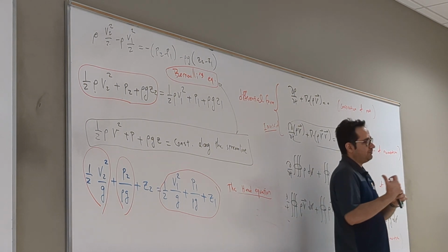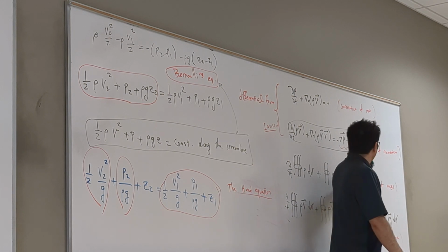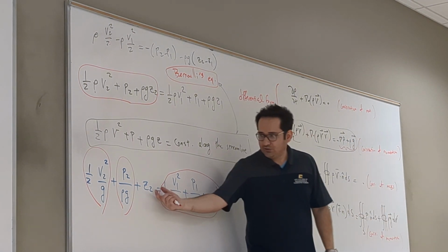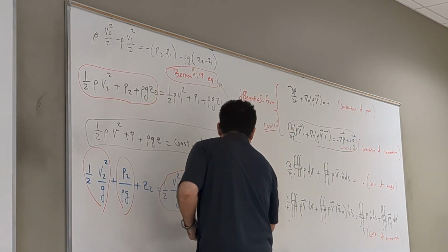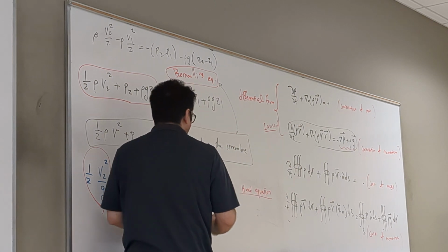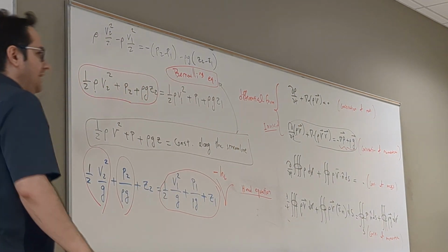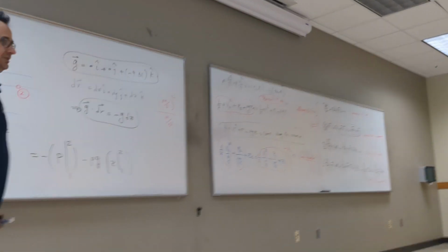In fact, we come to the previous chapter, which is the energy equation, and there is a viscosity, and you can model that. We apply viscosity here. With some derivation, you can show that there is actually a missing term here. That means this sum at point 1 minus head loss, HL, is equal to point 2. That means at point 1, you got some loss to reach point 2.